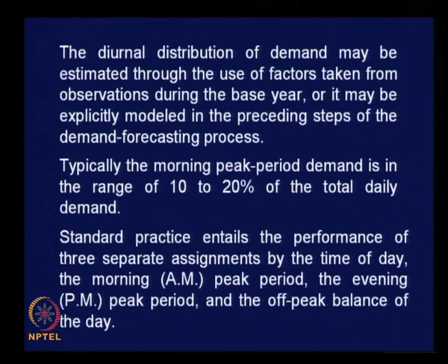As traffic engineers, you might know that you cannot have a single signal cycle for the whole of the day to manage traffic at intersections, even though in our country in many cases they just fix only one cycle time and manage to regulate the traffic. You should have different cycle times and different phase split, one for morning peak, one for evening peak, and one for non peak hours. If necessary, you can go in for more cycles also, and traffic signal should be really dynamic, because truly dynamic traffic signals are vehicle actuated traffic signals.